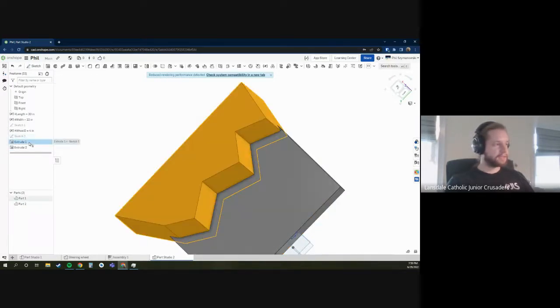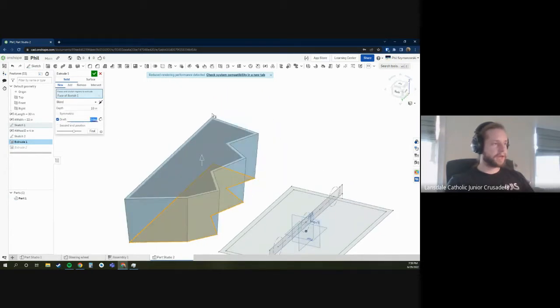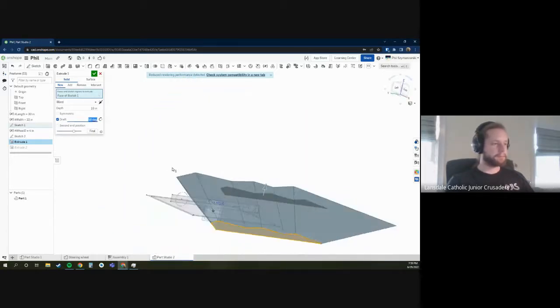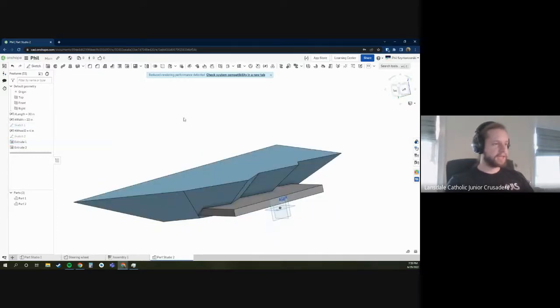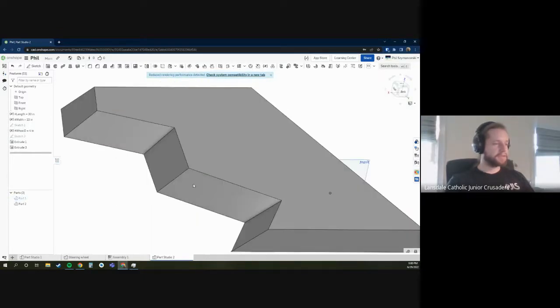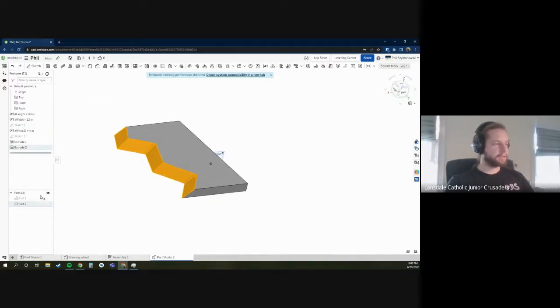And the cool thing is that anything that I change on this part, like if I change this extrude, if it now has a taper to it, which is known as a draft, maybe it goes like this, some kind of base for something, and it tapers out. If I did that instead, the part that I made previously still follows that same profile. It still has that angled cut because we told this extrude to extrude up to next.